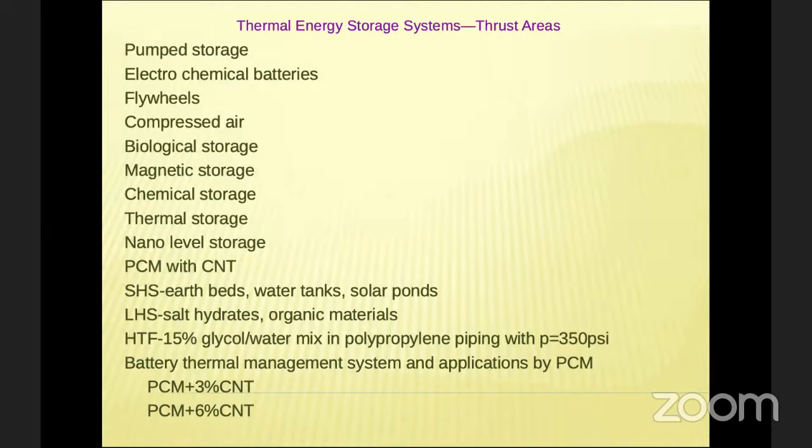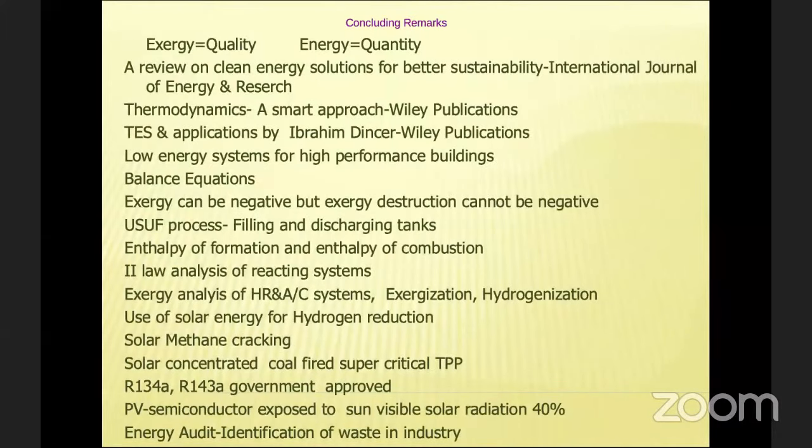Based on my presentations, what are the concluding remarks I want to tell? Energy is only a quantity. No thermodynamic analysis is interested in quantity; it is interested in quality. Many are doing biodiesel work or other work, simply writing some efficiency equations, and writing proposals or papers, right? People have to think that this is not the correct procedure of getting the efficiency, because we are completely forgetting the environmental effects. We are completely forgetting the exergy destructions. We are completely forgetting the exergy terms, useful exergy. So hereafter you have to take into account second law efficiency based analysis.